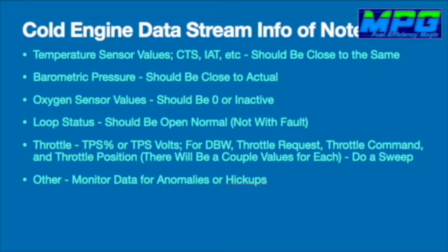So what we want to do is slowly step down on the throttle the whole way to the floor and watch those numbers. They should just gradually change with your foot. And then back off slowly. Watch for a hiccup, because a hiccup is going to be a bad spot in the resistive wiper. And just basically go down through and look at all of the data.